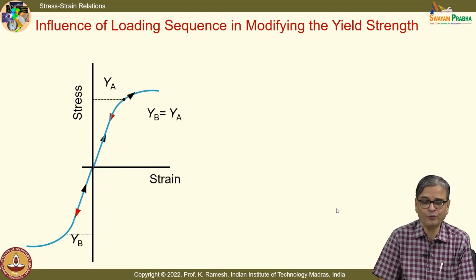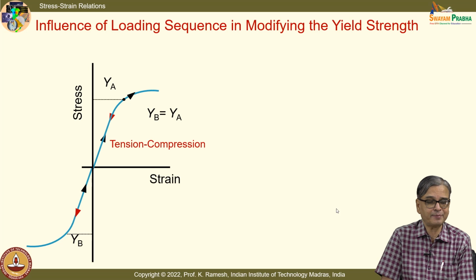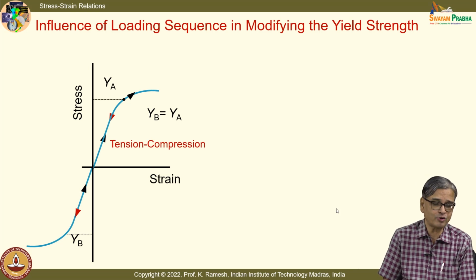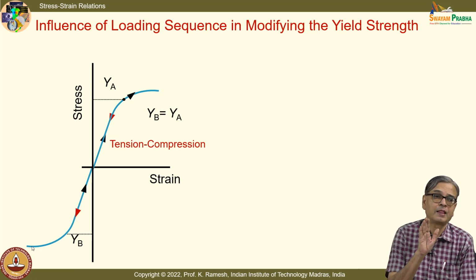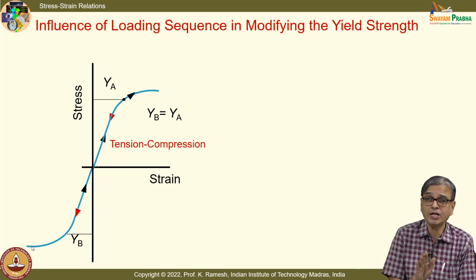And before we move on to the generic material, see, people also have looked at, suppose I take a ductile material, I pull it, I go to yielding, what happens? Then I also compress it and then go to yielding in the compressive zone. See, in the case of brittle materials, we saw Young's modulus in tension and compression are widely different.